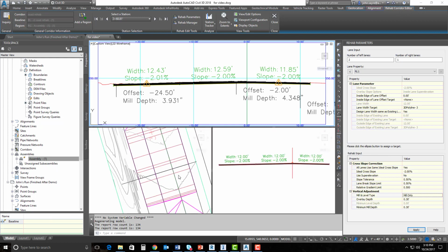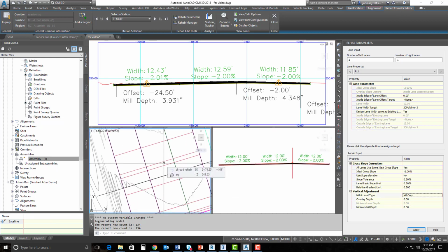That's the process that I wanted to take you through so that you could see from a LiDAR point cloud that was scanned, that was a backpack scan or a mobile LiDAR point cloud that was generated from a LiDAR machine that's on top of a truck or a vehicle of some sort that drove it. From that LiDAR point cloud, we can bring it into InfraWorks. We can pull linear features so that we can start to target things and use that information inside of Civil 3D. We can also generate transverse features that allows us to pull points along that particular line or at a station increment.